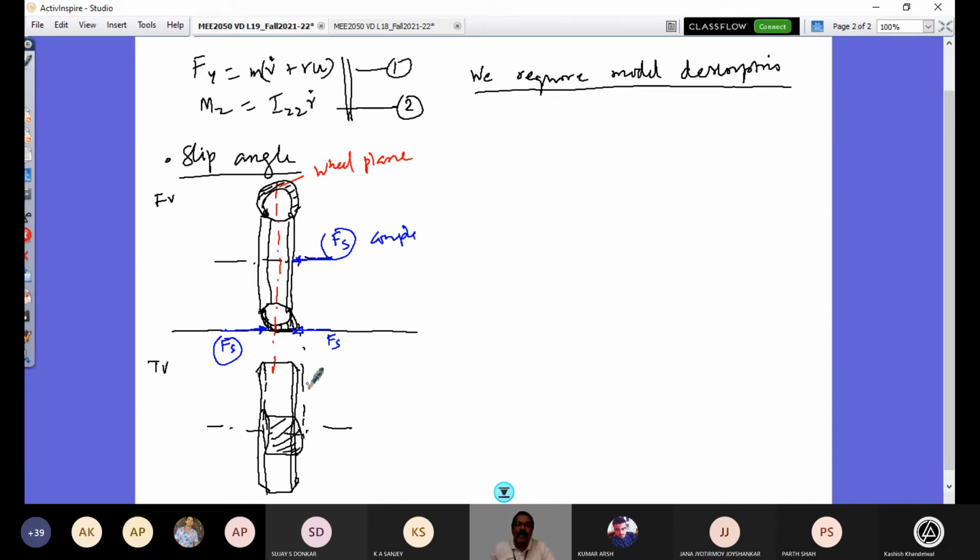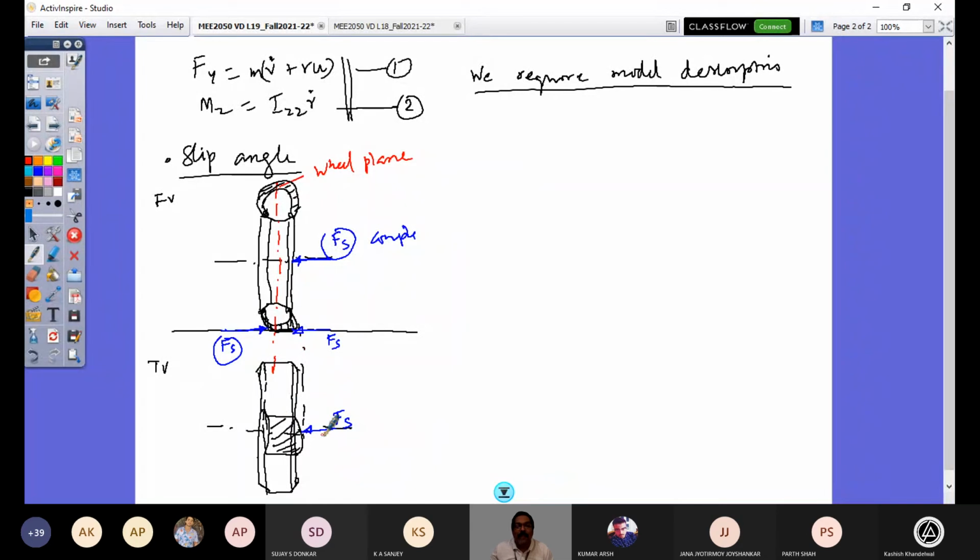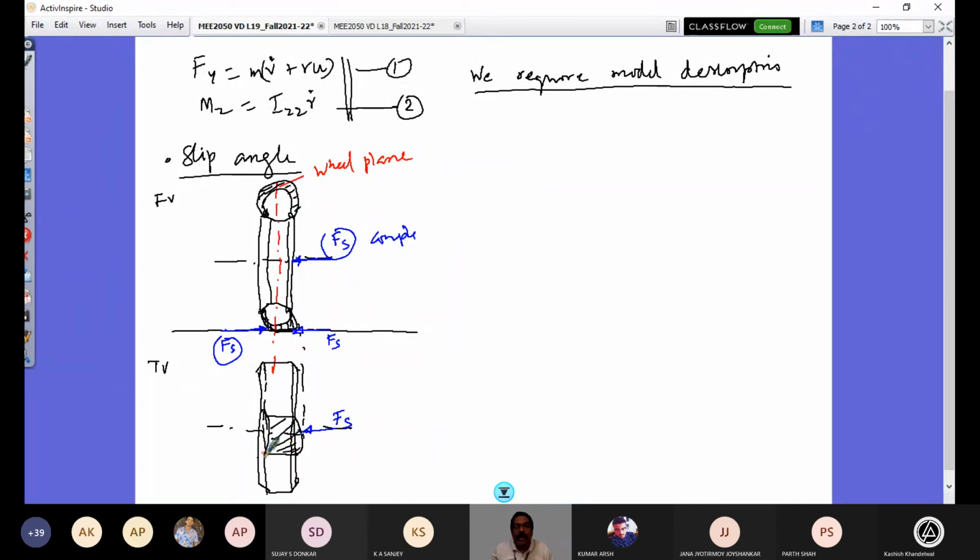And in the top view, this Fs would be here now along this. I just have brought it down to the ground. So you'll see in the top view like this. I don't show this couple now for convenience. And rather you see this Fs now, to balance, which is there here. The balancing force is not on line. It is offset to this, somewhere here, exaggerated. So this is my Fy. So this Fy is what is balancing. And this would act at a distance from here called Tp. That is called pneumatic trail.